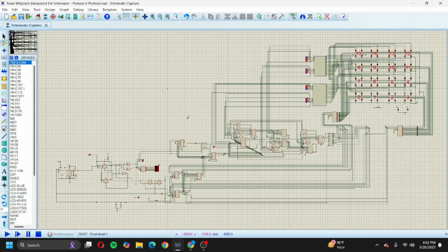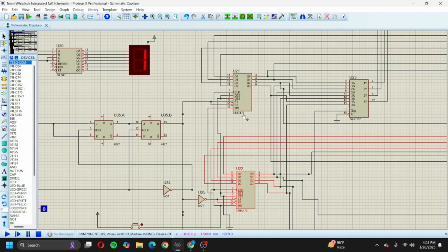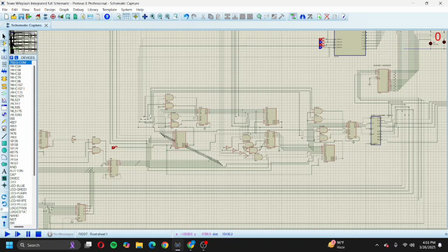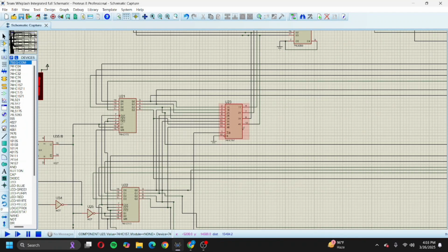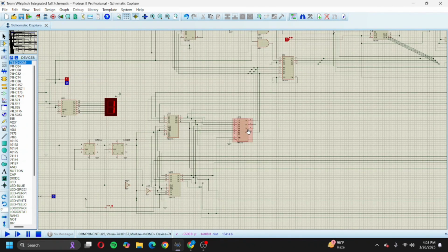Now I'll be explaining the memory module. Initially in the phase CDE, the file we submitted had some issue in the memory module. That's why we had to keep the memory module out of the subcircuit. Then finally, before submitting the files including PCB designs, we fixed the issue. Now the main part of the memory module is basically 2 D flip-flop registers, and because the logic module can only flow one player's data at a time, we had to use these 2 to 1 line muxes, for selecting each time the active player's data to go through the logic module.